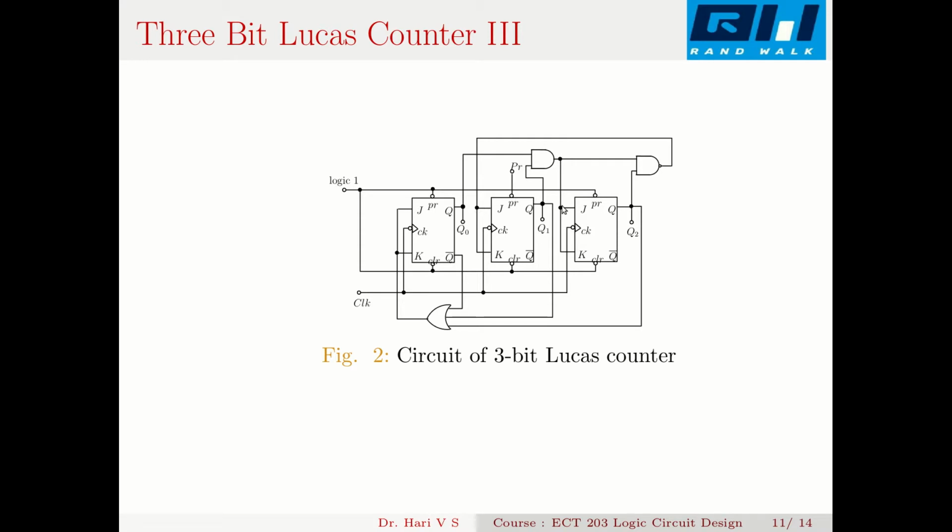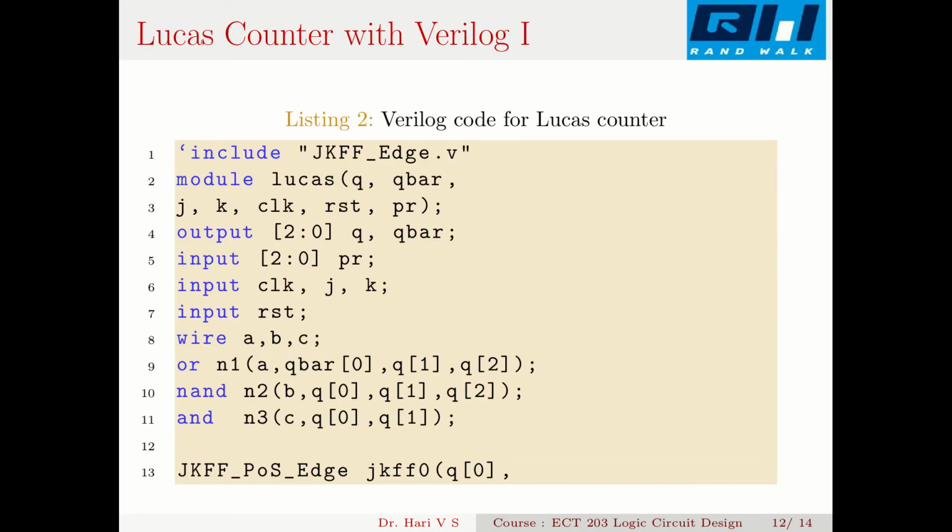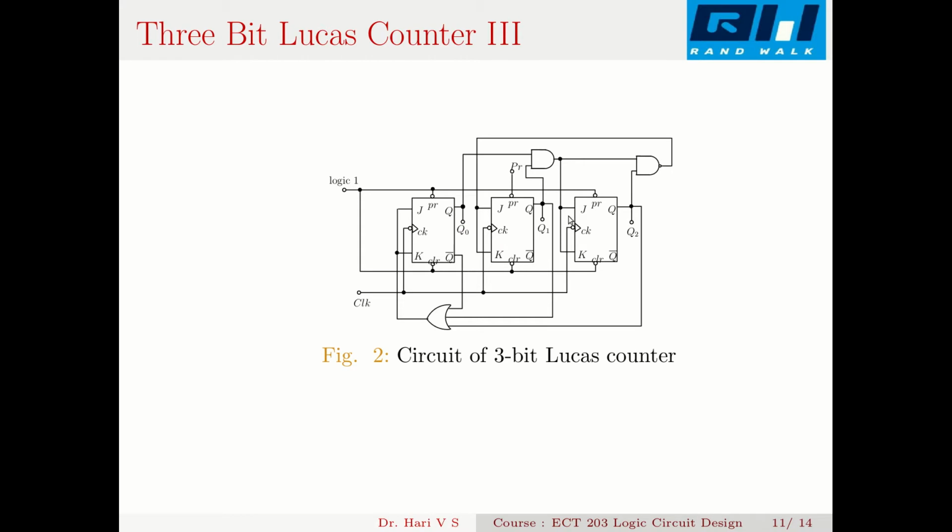At J2 and K2, what do I apply? That is Q1 and Q0. I apply Q1 and Q0 to J2 and K2.